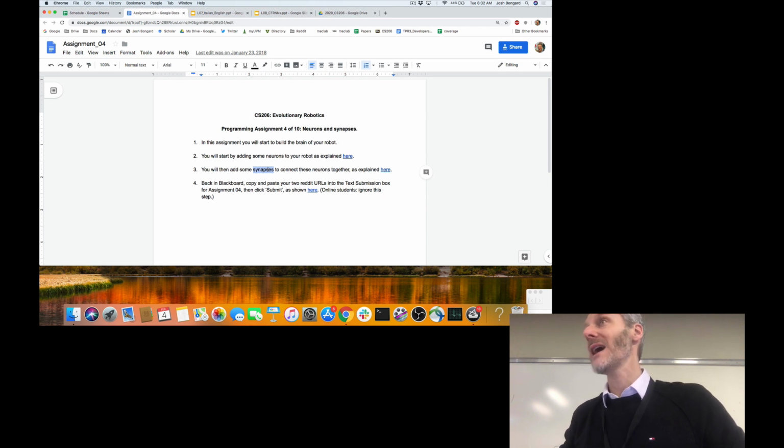If you change the synaptic weight, what does that do to your robot? What does that do to the behavior of the robot? Changes the torque that's applied to the motors given the same sensor input, which means the robot will react differently if it senses the same thing as it did before the change to the synaptic weight. You can also make physical changes to the robot, elongate or shorten the cylinders, change their mass, change their radii.